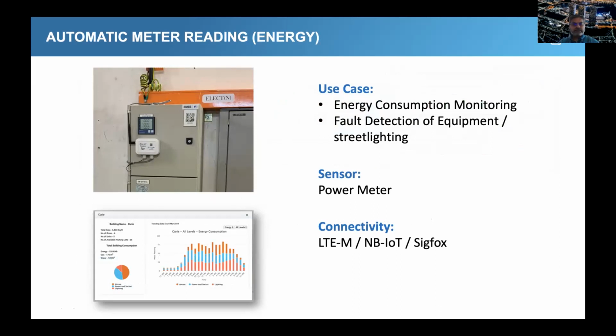But in this case, it was a university campus that had hundreds of street lights outside. They didn't have a budget to buy smart street lights, right? So what we did was we connected our device to the electricity distribution box and monitored the current consumption of the different lighting zones. And depending on some variations, we could detect failure of lighting based on the current data.